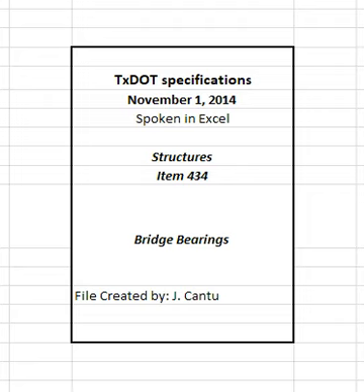Refer to the plans for temperature setting corrections for all bridges and bearing alignment relative to chord for curved bridges. Perform such adjustments as directed if the plans do not address these requirements. Exercise care in any field welding required for the installation of an HLMR bearing to prevent damage to the elastomer, disc element, PTFE, or stainless steel surface. Perform repair of damage to the prime coat on the bearings and apply the final appearance coat in accordance with Item 446, Field Cleaning and Painting Steel. Damaged bearings will be subject to rejection and require replacement as directed.